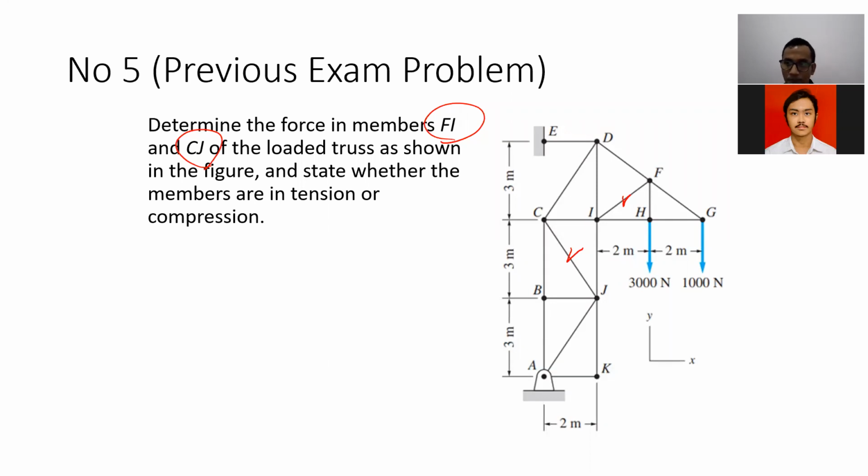I think two. Yes, it is correct. We cannot solve this using just one section, because one section can only solve for three members.